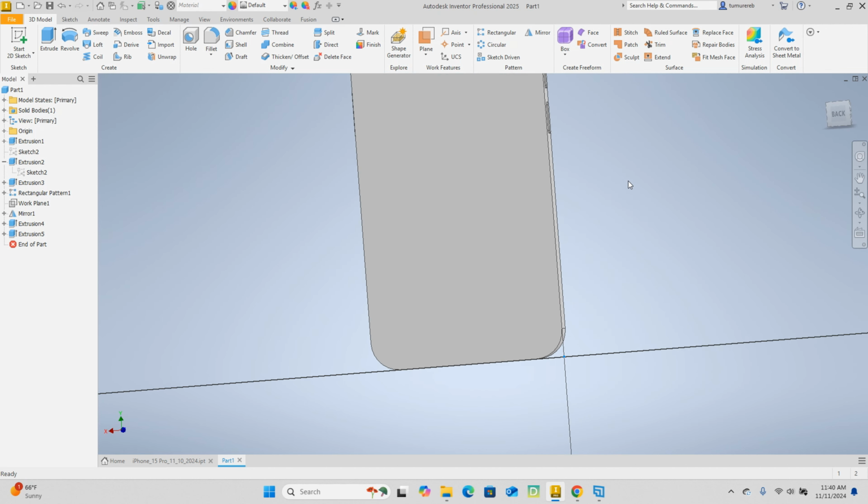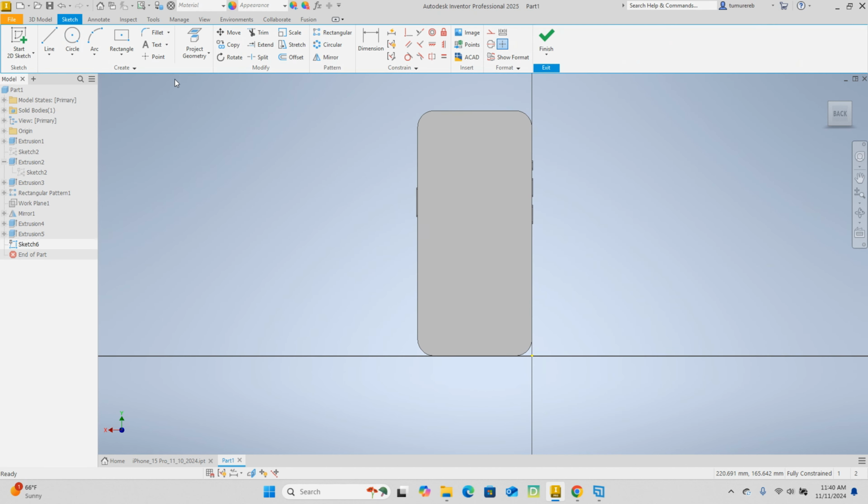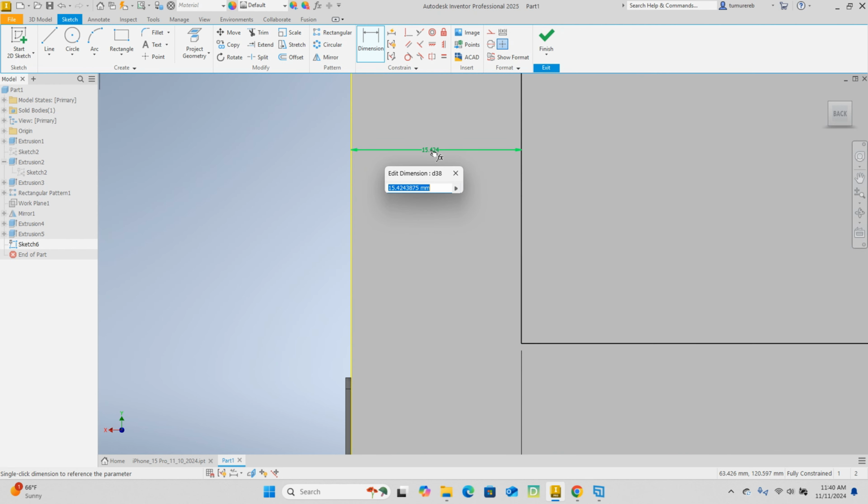Start a 2D sketch on it. I'm gonna draw a 2-point rectangle. It's actually gonna be a square. The length is 38 by 38. Okay. Right click. Alt escape. Now, from this side to this edge, the distance needs to be 5, and also from here to here, the distance needs to be 5.